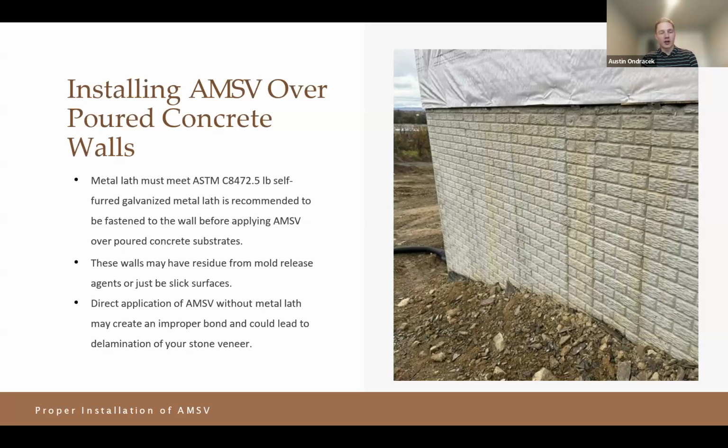And then just a note, direct application of AMSV without metal lath may create an improper bond and could lead to delamination of your stone. So not saying it will or it can or it will happen, but there's a greater likelihood that later down the road, maybe something could delaminate if not installed with a metal lath.